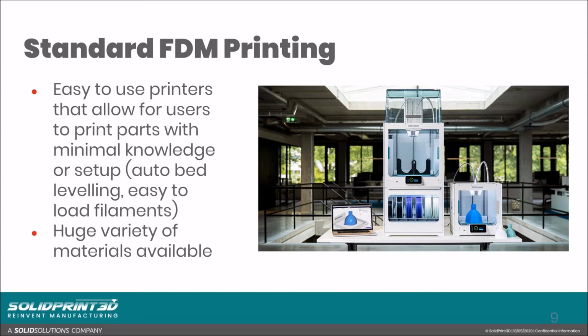Also, being able to scale up FDM printing to larger bed sizes is something that's more obtainable, whereas with other 3D printing technologies, it can be a little trickier to print larger scale parts. So if large format 3D printing is something that is important to you, then FDM 3D printing is probably going to be worth looking at as well.